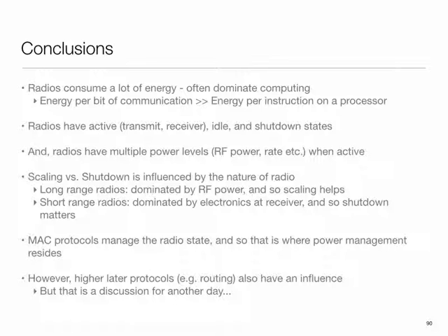So at this stage, we can get down to 1 to 2% duty cycling with commercial radios while achieving a few kilobits of data rate. If you need to go down to, let's say, 0.1% duty cycle or those kind of things, you basically have to use some of these other protocols which are still in the research stage. Some of the applications have requirements which are maybe 0.01% duty cycle, and we don't know how to achieve them because at some stage clock becomes kind of a bottleneck.